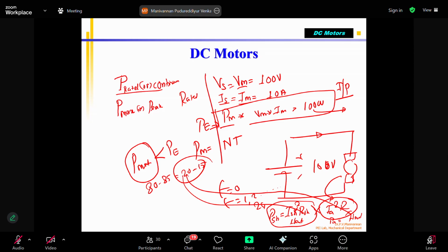Because air is supplied inside the motor to cool it. You will see that internally it will be closed, and there will be a small fan to remove the heat generated in the coils. So the air is going, and that also creates some resistance. It opposes the motion of the rotating armature, along with the bearing friction. All these are mechanical losses, I say P mechanical losses. So P electrical minus P mechanical losses will be equal to the mechanical output, which we call the shaft power, which will be around 80 or 75 percent, depending on how good your design is and how much friction is removed.